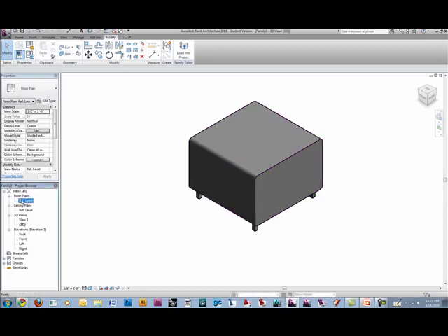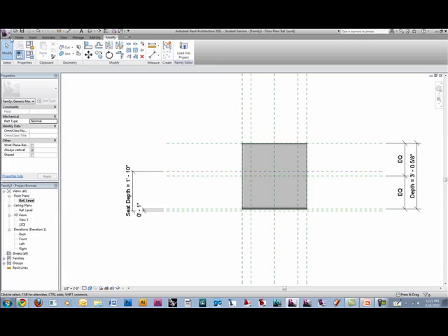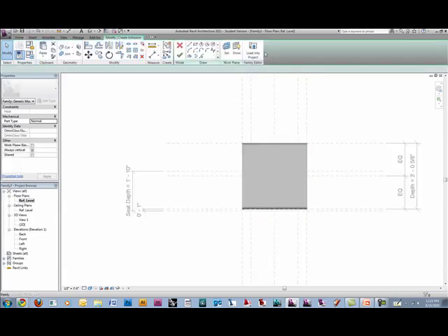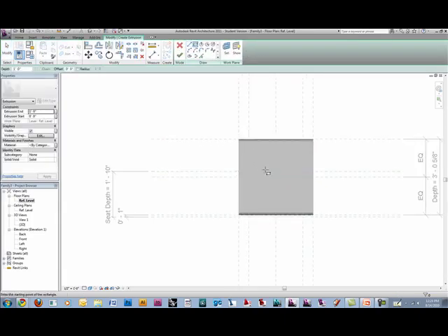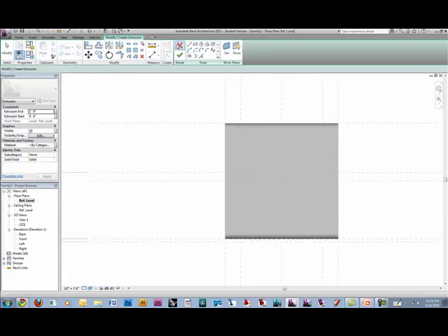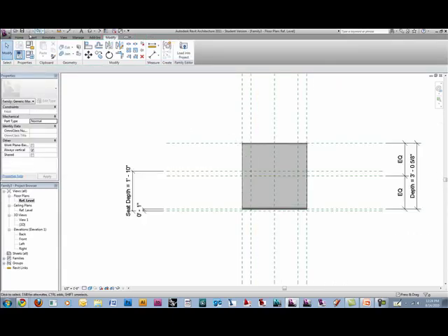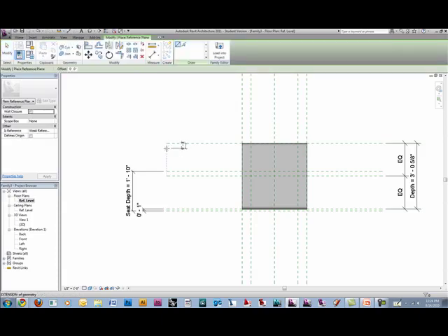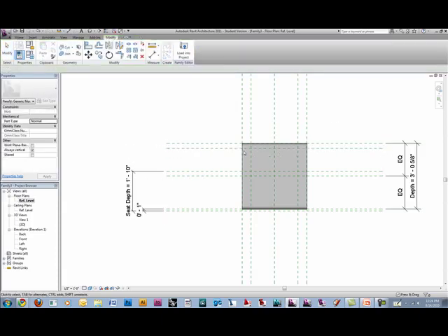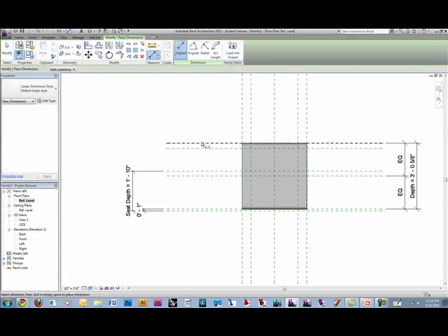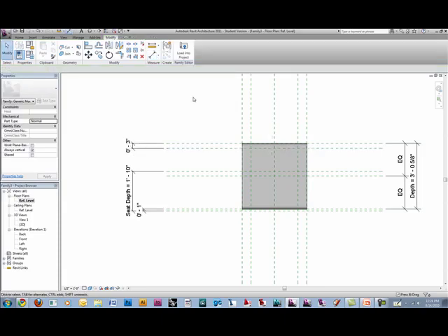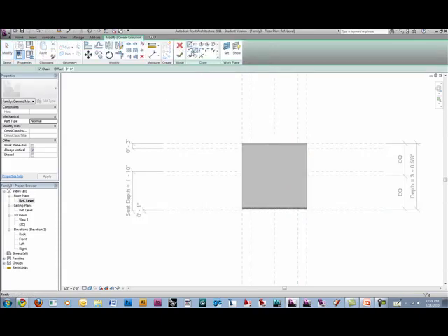So we go to our reference level. We're going to create another solid piece of geometry. Rectangle, rectangle. You know what? I'm going to put an offset in the back. That's the other one I forgot. So maybe, I don't know, we'll try 3 inches. I think that's what it was last time. And we'll tell this to be locked. This is for the back part of the sofa where the cushion leans up against. So, home extrusion. Now we're good to go.